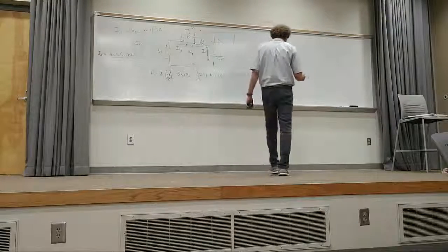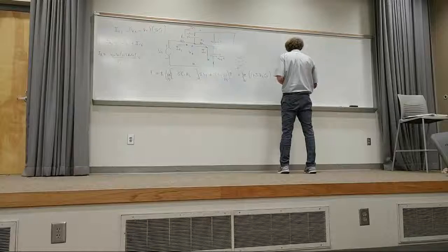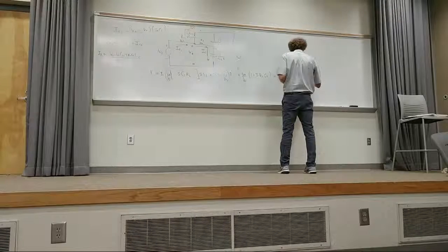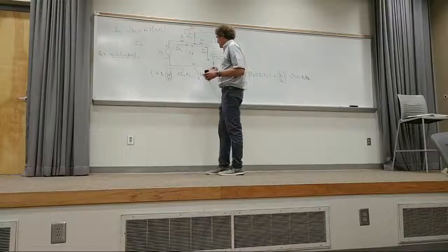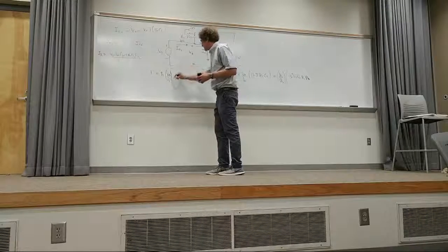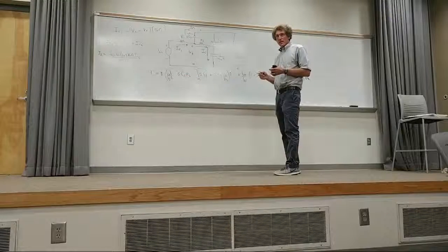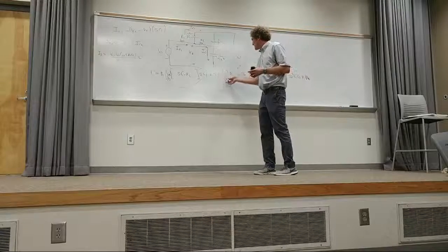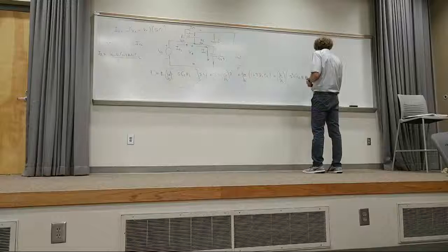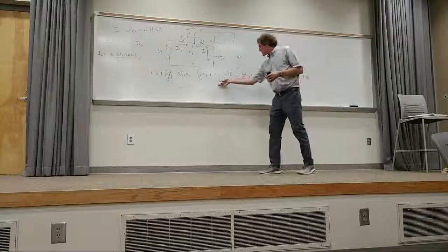Right? But there's also an SC1 here, right? So that makes this a squared, and I better put this on here, so it's now S squared times C1, C2, R1, R2. That's this entire term here. It's the coefficient of V out over Vs. Do you agree with that? Keep going on this one. You see the coefficient of V out over Vs here is SC2R1. That's this. With me?